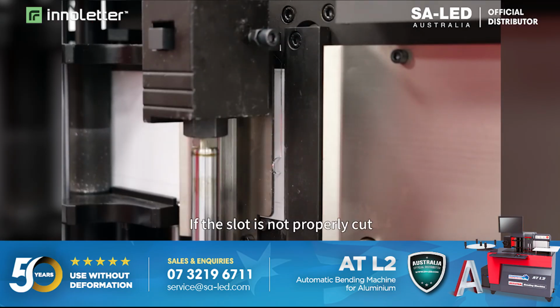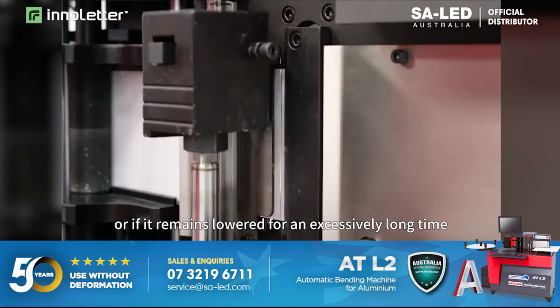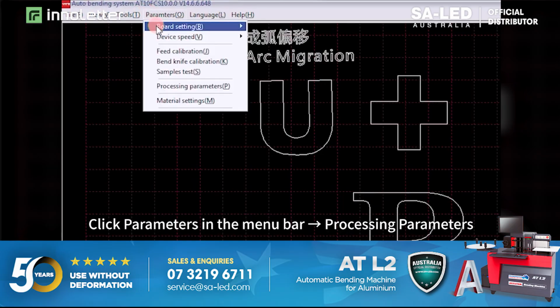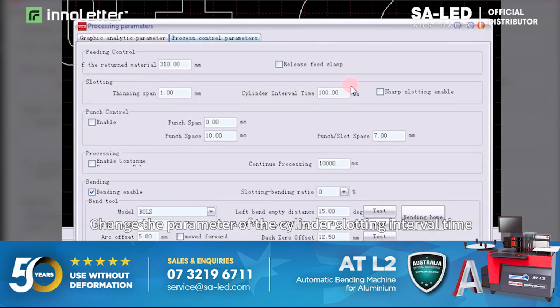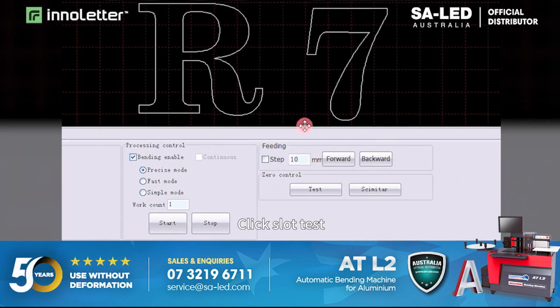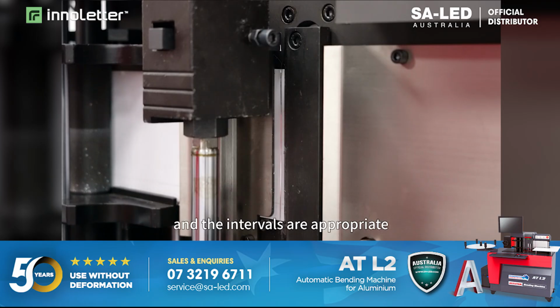If the slot is not properly cut, or if it remains lowered for an excessively long time, please follow the operation procedures below. Click Parameters in the menu bar, Processing Parameters. Change the parameter of the cylinder slotting interval time. Click Save. Click Slot Test. Debug until the complete slotting is achieved and the intervals are appropriate.